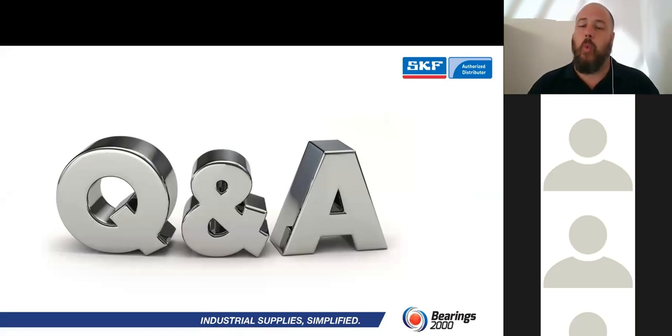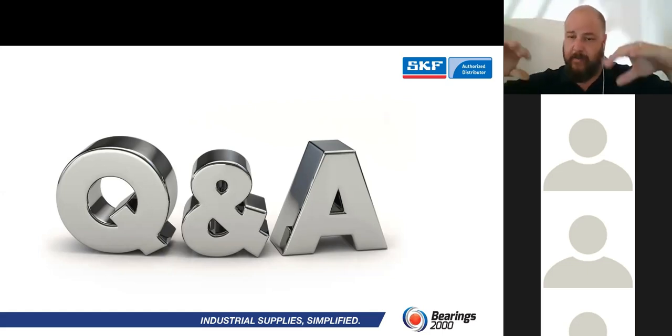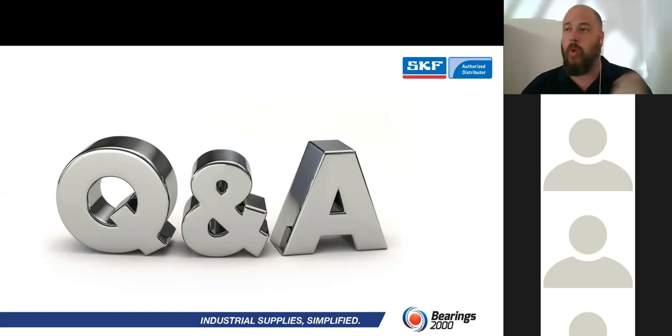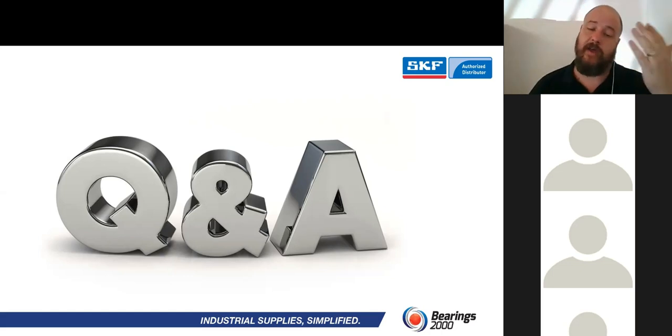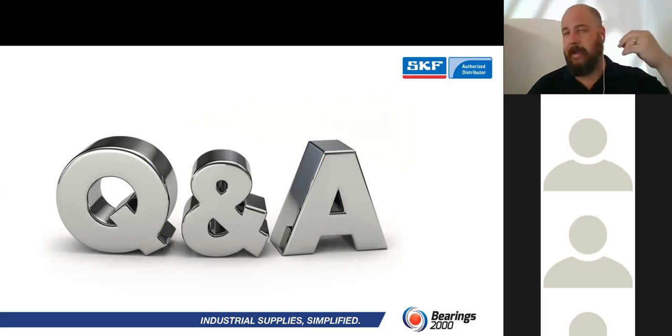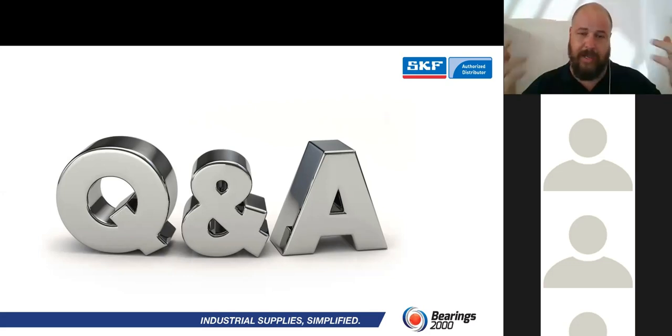They will give you what the tolerances are. Now, all of them are ISO tolerances. Some of your other tier bearings will fall under JIS, which is the Japanese Industrial Standard, but most of them are under the ISOs, which means they will have a minimum and a maximum factor. So you will measure a 22218 clearance, spherical roller bearing clearance, with a feeler gauge, and you will have an allotted tolerance, which is, just off the top of my head, say between 100 and 120 microns.